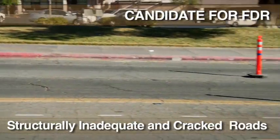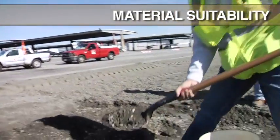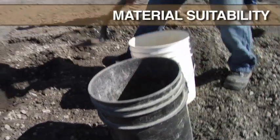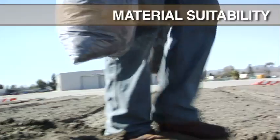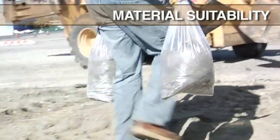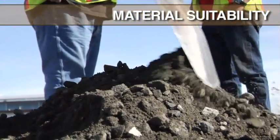Proper site selection is an important part of having a successful project using FDR-EE. Not all materials qualify to be treated with FDR-EE. A qualified geotechnical engineer should perform a materials evaluation to determine if the road is suitable for this process. These samples can then be submitted to a qualified laboratory to develop a mix design. A little homework can save agencies money and make sure that they are getting the very best solution.